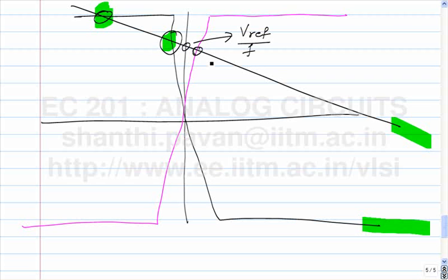It turns out that solution is an unstable solution, and I won't go into the details of why the solution is unstable, but you can think of it in this way. Let's say the system is settled at this point, and there is a small disturbance in the system. In negative feedback, when there is a small disturbance, the feedback loop tries to restore the original operating point, because if there is a disturbance, the feedback loop will react in a way as to eliminate the disturbance, whereas in a positive feedback system, it will try and enhance the disturbance.